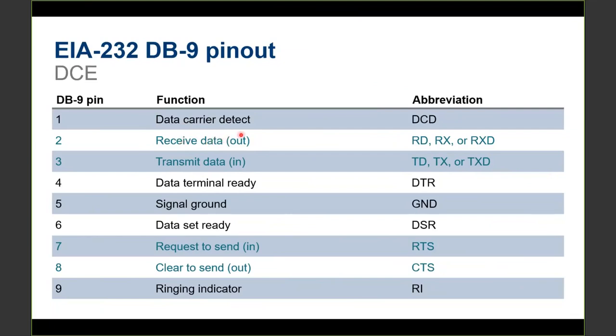You receive that data and push it out on pin 2, and then the end device, we're going to say it's a relay, has this DTE communications on. So pin 2 on that receive device, or that DTE device, is to receive that data in on pin 2. So we followed basically from the RTAC and went out pin 3 into pin 3 of the first modem, transmit data in, and then of the second modem, now it's received data that it's received, and that comes out of pin 2 and goes into pin 2 on the DTE configured relay.